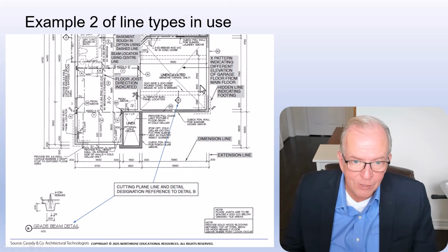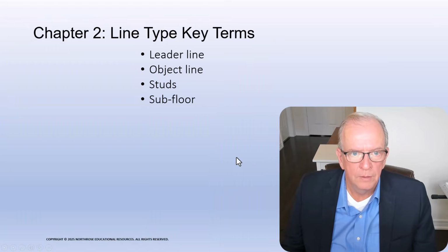Always expand your field of vision. Don't get so hung up, saying it's not there, I don't see it. You'll be surprised how many times the dimension is there that you thought it wasn't. The other thing is you'll notice there are some notes peripherally. Always look around the edges for any kind of notes, because these get missed very often.